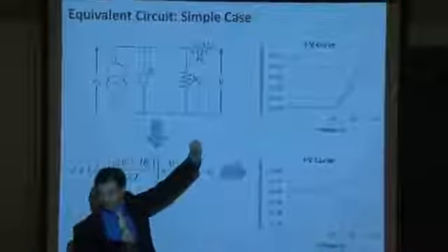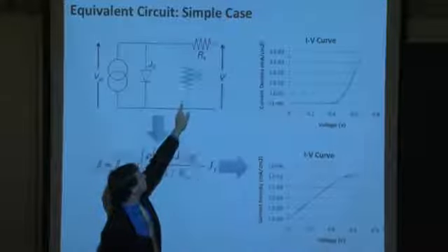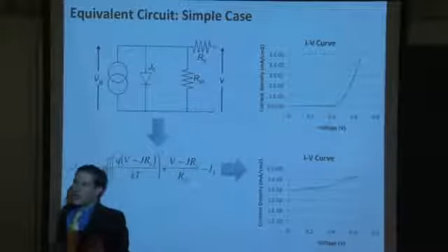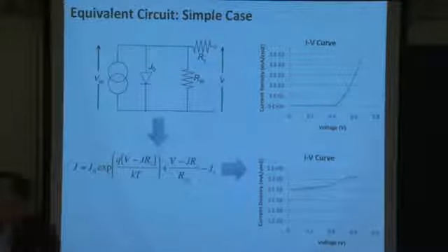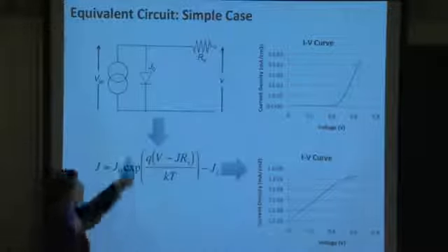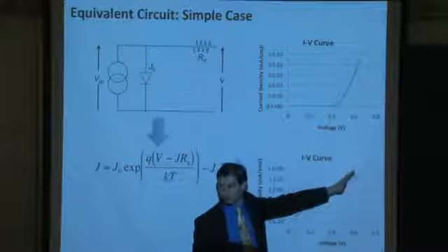Likewise, we're going to introduce another resistance term inside of our equivalent circuit diagram, what we call a shunt resistance. Now let me back up one step here. This was just with series resistance. Now I've added a shunt resistance term here as well. And whereas we wanted our series resistance to be small, right? The smaller our series resistance, the less this effect would be, the more ideal this curve would be.